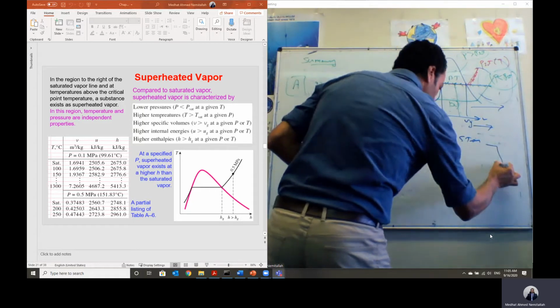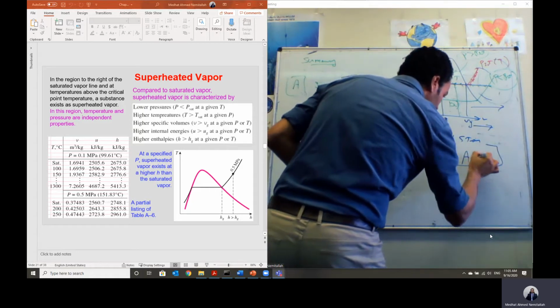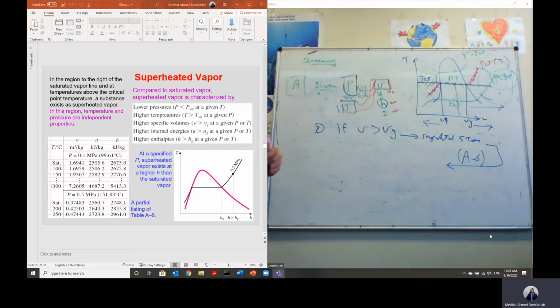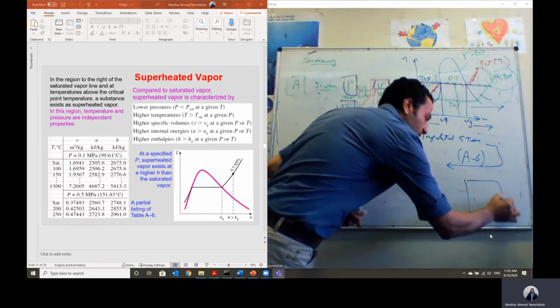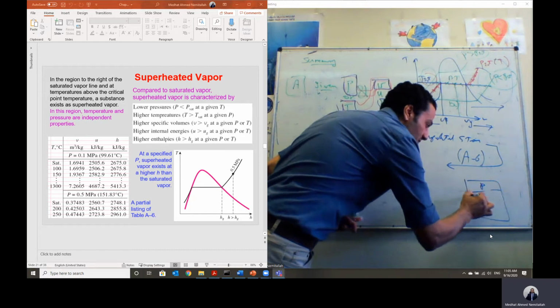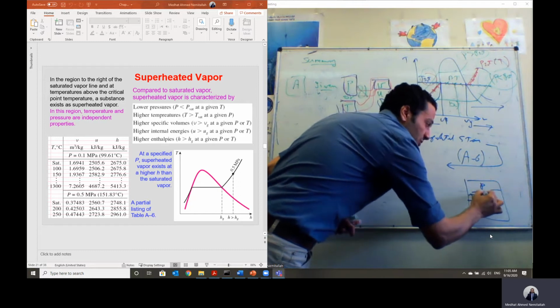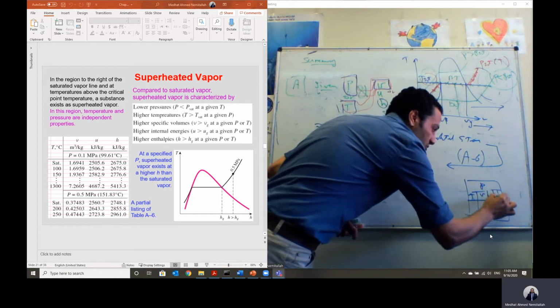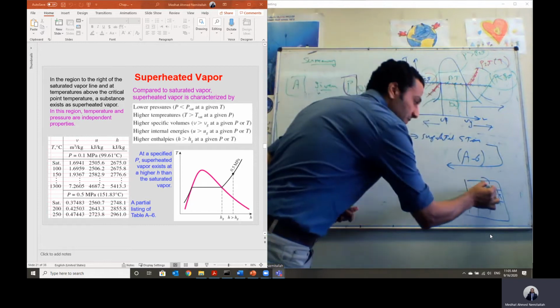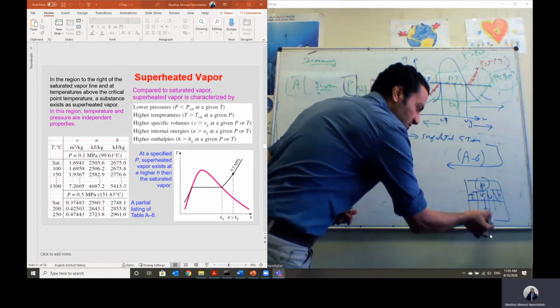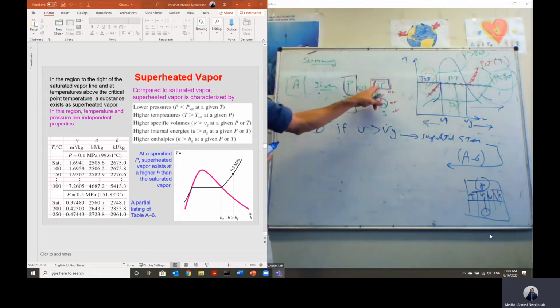And in this case, for the superheated steam, I have to use table A6. Okay? Given the pressure, I can define which pressure table I will be using, and for a range of temperature, you can find V, U, H, and S. I will specify the pressure table, then go under a specific volume. A specific volume is given.